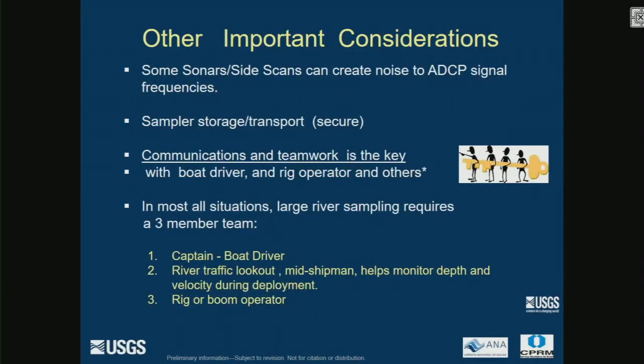Other important consideration, some of the side scans, be careful, because they can create a noise signal that interferes with the ADCP signal. And so if you're making your actual discharge measurement, you want to have these side scans turned off. You can get some errors. Storing these samplers, these heavy samplers on the boat, they need to be chained down. You don't want these things rolling around. Communication and teamwork is the key with the boat driver, the rig operator. It's a team effort.